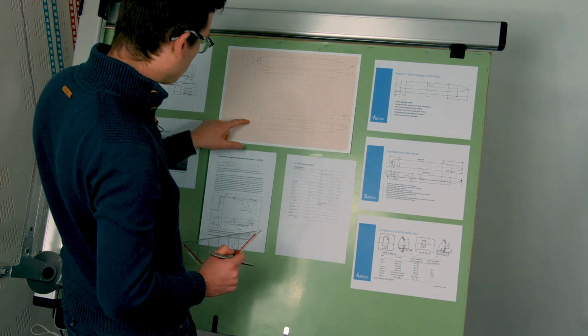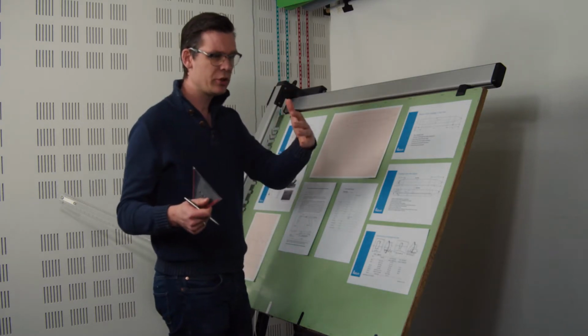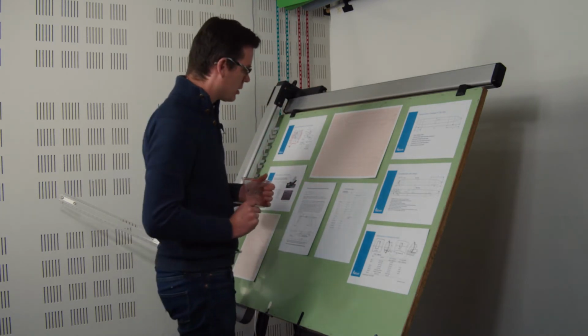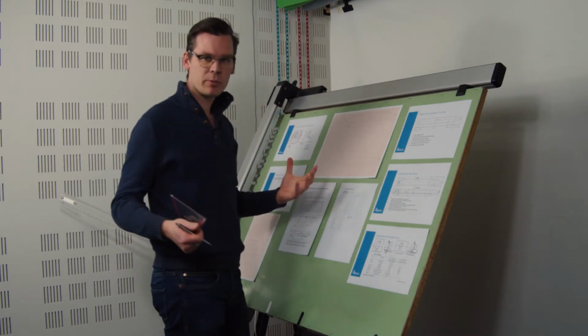Now the pilot is going to be quite close to the front, because the closer he is to the windshield, the smaller the windshield can be for a given over nose angle and upward viewing angle. But he cannot be so close that there's no space anymore for his legs and his arms, and also not for the instrumentation.